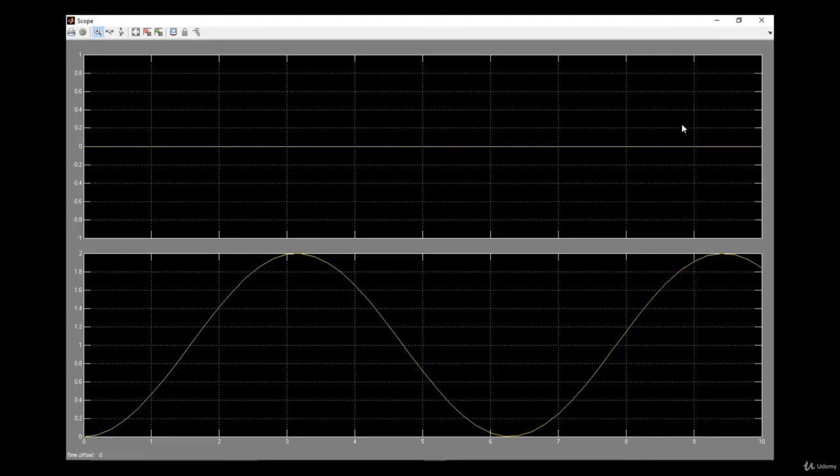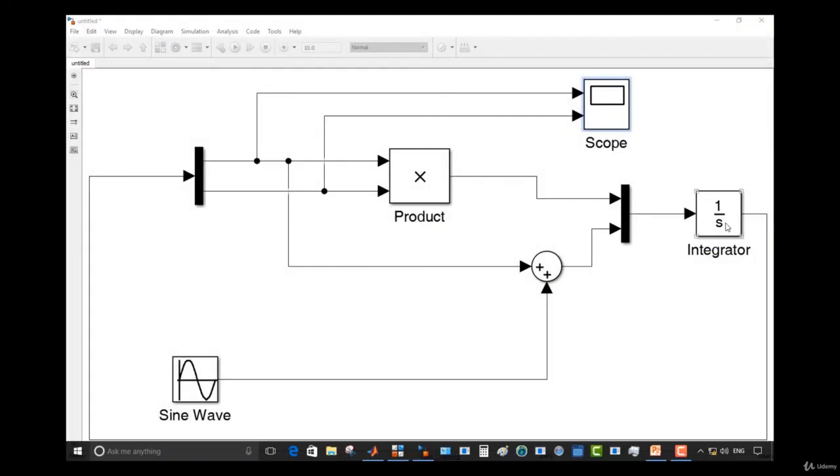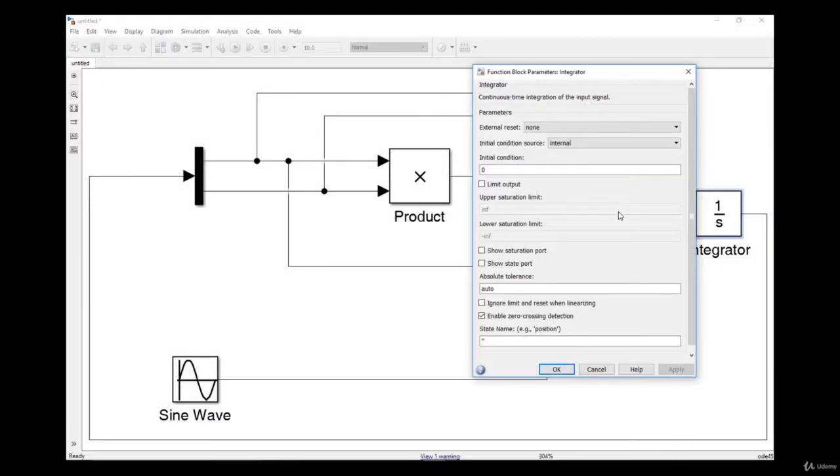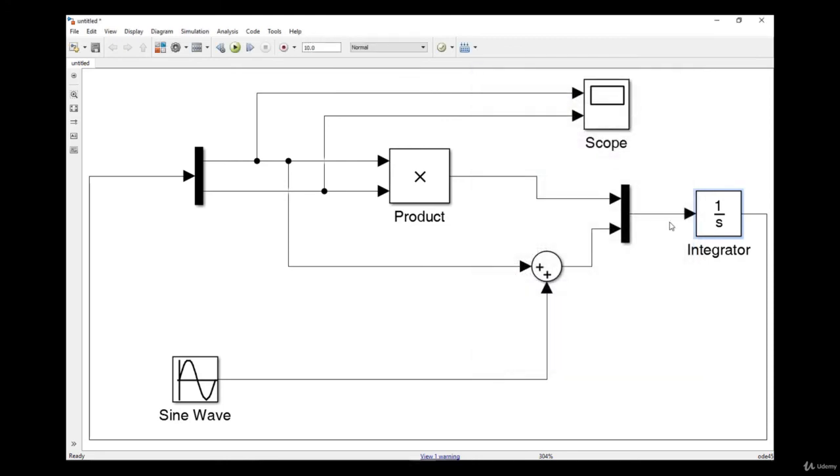Now, in order to change x1, I change the initial function in the integrator. Pay attention that two signals have been entered to the integrator, which was done by mux. So any amount which we enter to the initial function should be set for other amounts too.